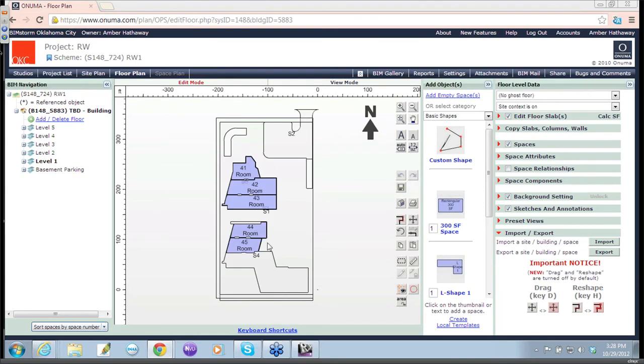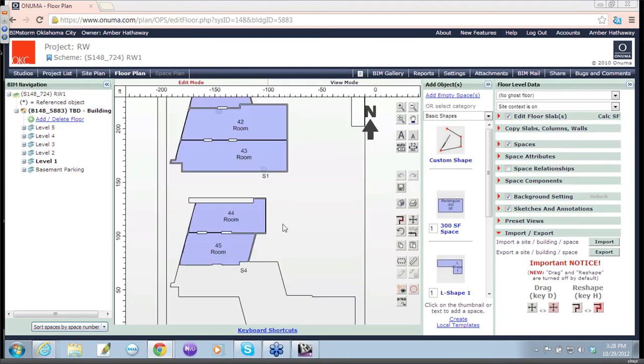Yeah, so there we go. There's your model spaces. The system itself will be capable of importing the spaces as long as they're placed, and it may just be a matter of using your rooms, your walls, and your wall separator or room separator lines, and then placing the rooms like I showed. So I hope that helps a little bit. Right, and so once they've done that, then the building square footage should all match.